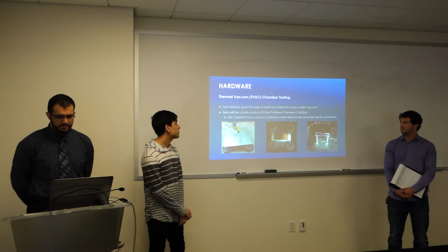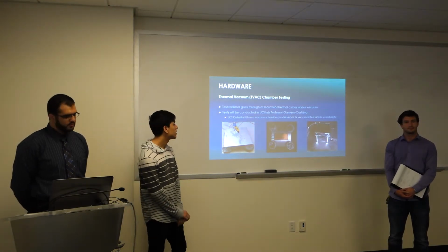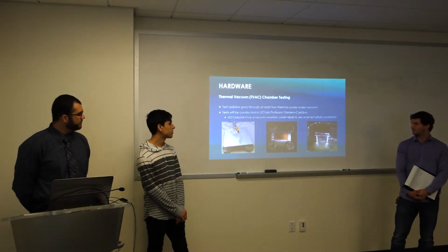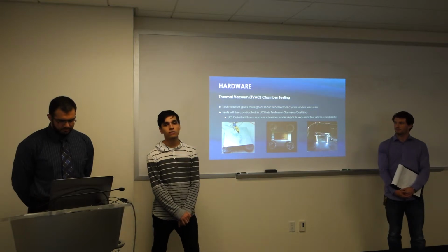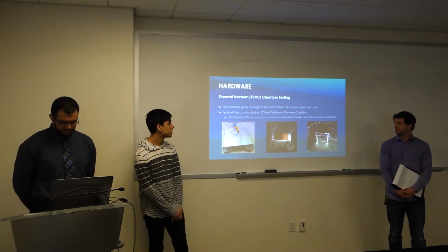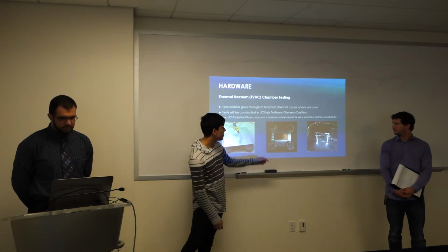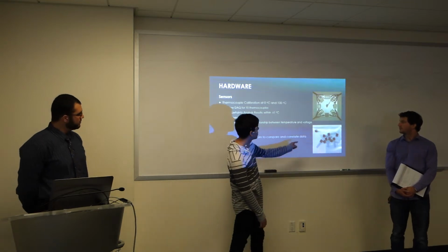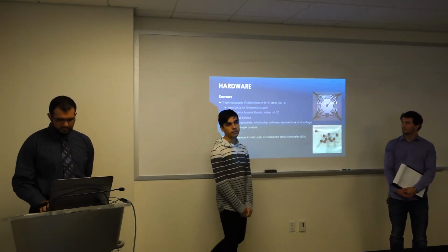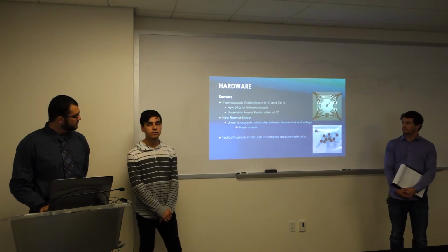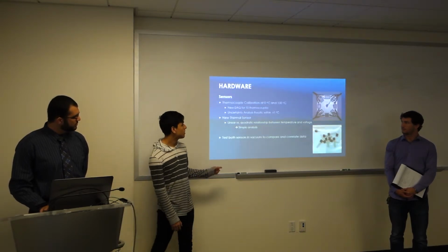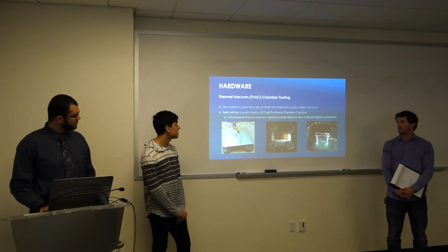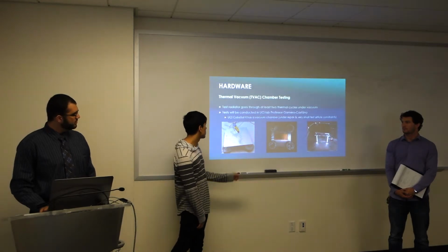So like I said, we're going to be doing a minimal vacuum chamber test. So this is the new plate. It's right here, that's the bottom side. The major improvements between the new plate and the old one is how we're heating it up. For this new one, we're using a heating strip instead of the previous one. The heaters in the previous one were these little rectangles right here, and then they were wrapped with wires, and then a voltage was applied. It's pretty much the same concept with the heating strip, but it's just more precise. And we're also using the new sensor, like I said.